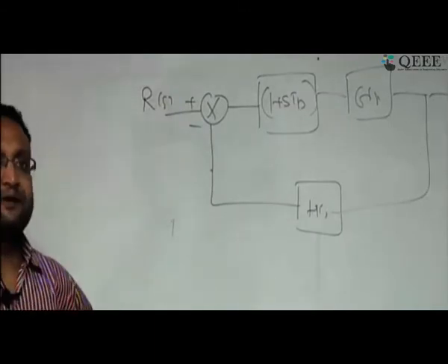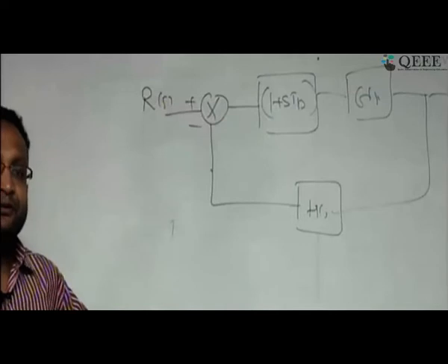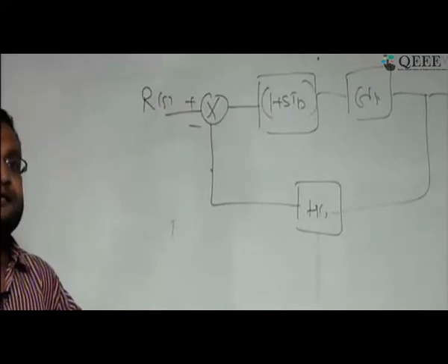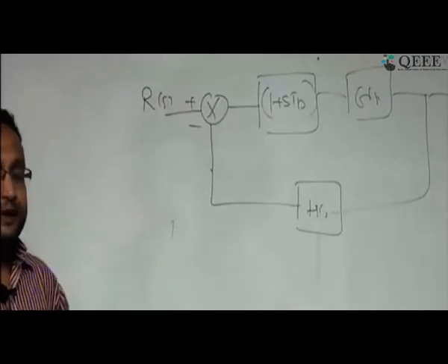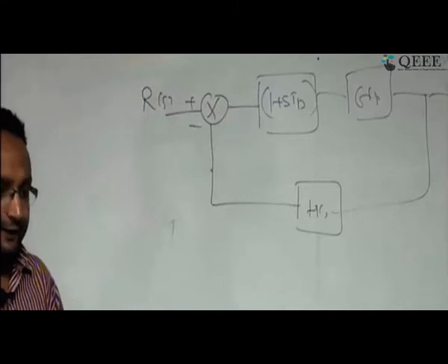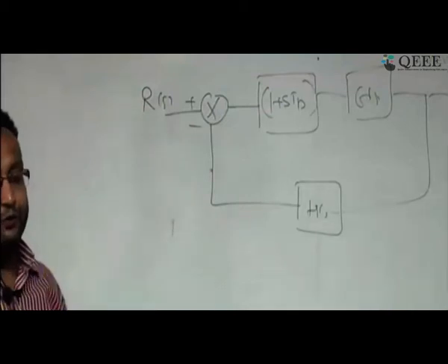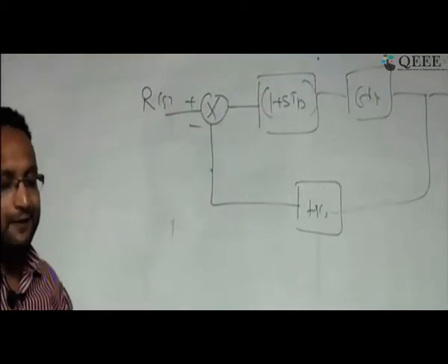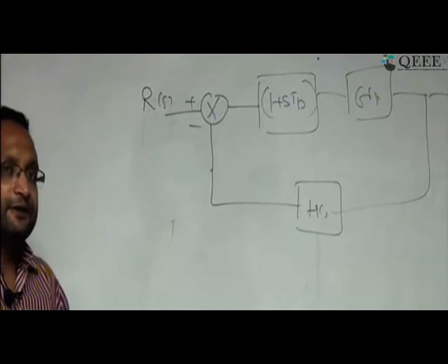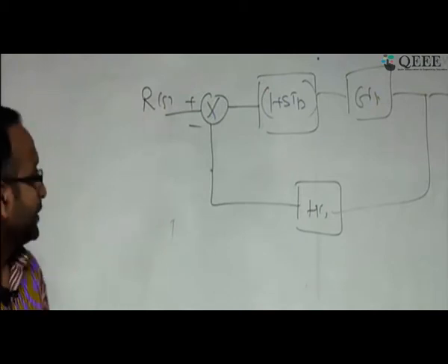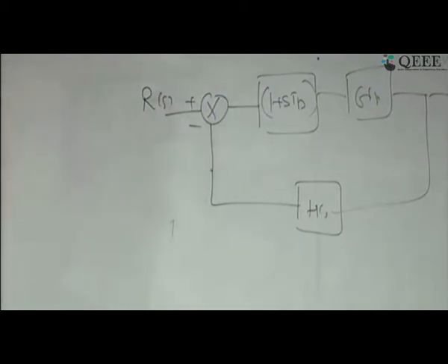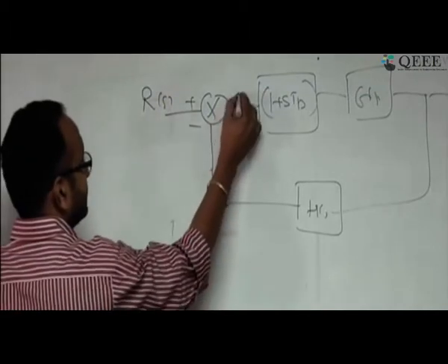If you add a derivative controller, it is very good. It is very intuitive that it will tell you whether the error is increasing or decreasing, and it's a good way of working. I have also explained the intuitive way that it helps to improve your settling time, and hence it will help you make your system faster. Now one important thing is that suppose this error signal.